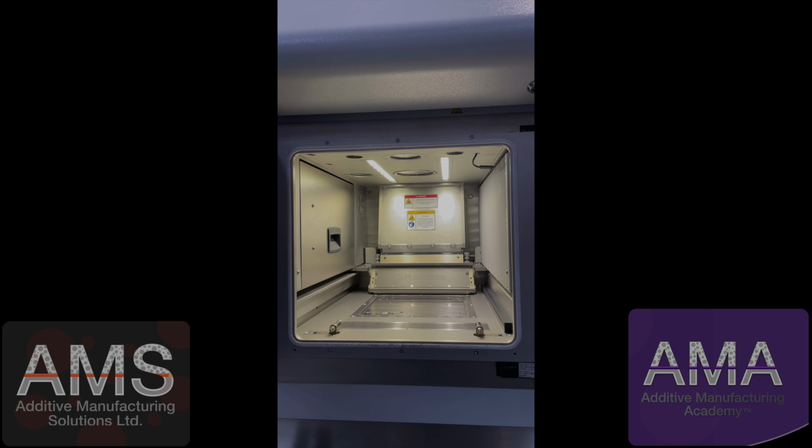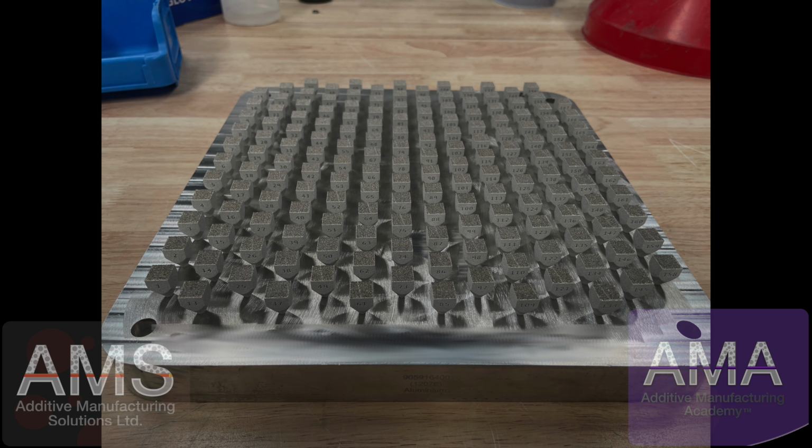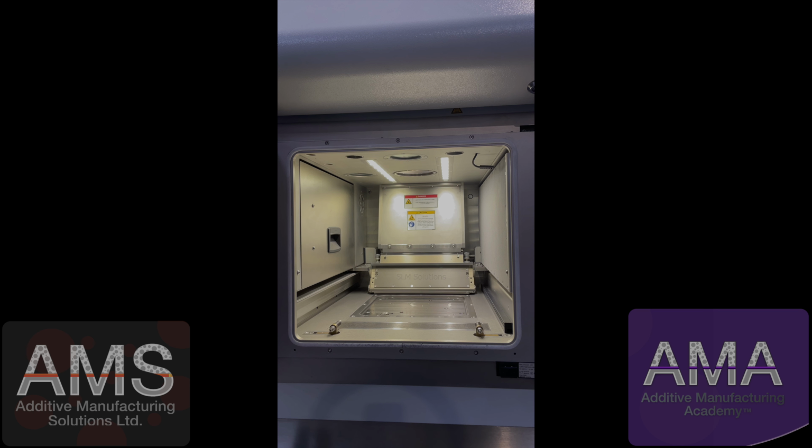We will then remove all of the surplus powder from the build chamber, normally using our cyclonic separator, to be left with the final part that we wanted to produce. That's the fundamentals of the powder bed fusion process within our SLM 280.